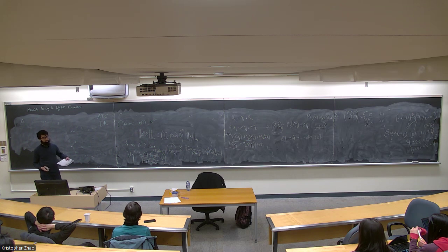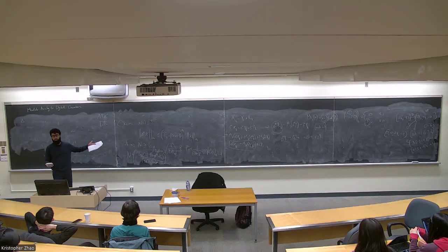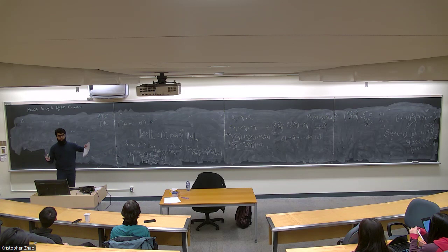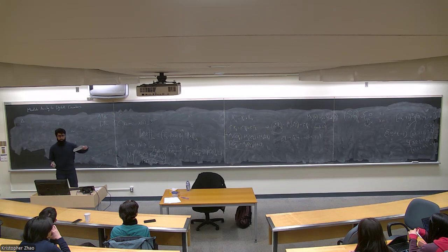So the big goal is to go from those samples y sub k. We first had a function or a signal x of t. We applied the modulo operation to that to produce y of t. Then from y of t we have the discrete samples y sub k, and from x we had x of k. At the ADC we only observe the samples y sub k, we only observe y of t. So you want to recover the samples x, knowing only y.